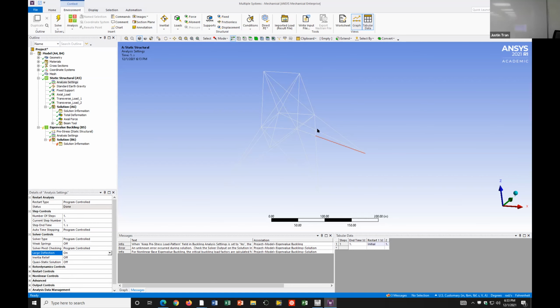So from a design standpoint, you would hope that it can withstand all of these, so you would design it around the first one. You want no buckling at all. So really the one that's most useful 99% of the time is just the first one. You want to make sure that your buckling multiplier, you can consider that like the factor of safety. If you apply a load on here, you want the multiplier to be like 3 or 4 or 5, meaning this load can still increase by a factor of 3 to 4 and you can still launch it. But this is a unique case because these are less than 1. Usually you don't want this, because that means your structure's already buckled. Most of the time you want it at least over 1, but the higher the better. So if you tested this multiplier out and the force you're expecting is larger than what this would give you, then you can say, oh, this is way too weak. Exactly. Okay. All right.